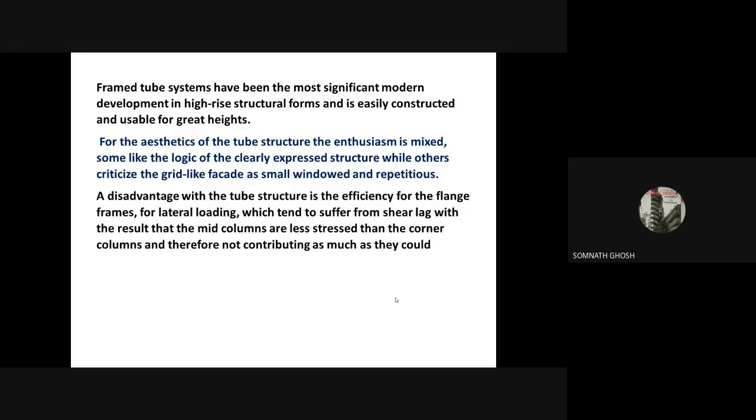The drawback of this tube structure is the efficiency of the flange frame for lateral loading, wind or earthquake, which tends to suffer shear lag, with the result that the mid columns are less stressed than the corner columns, and therefore not contributing as much as they could.